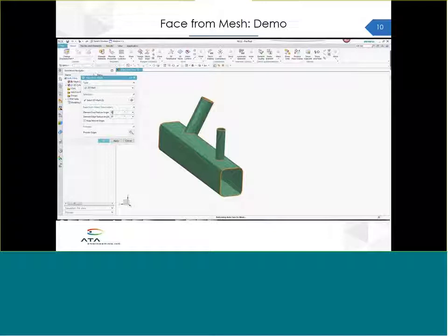Decreasing this parameter will create more polygon edges. What this parameter is essentially is the angle between adjacent 2D element normals. So the command will create edges when the angle between normals is greater than the specified parameter. So I'll give this a random angle of 20 degrees.